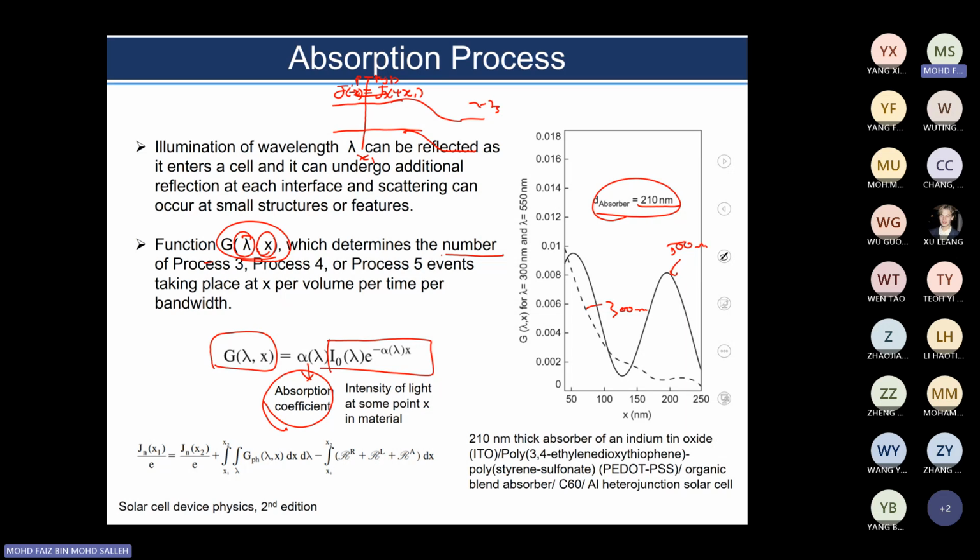However, in the PN junction, we give photon energy, and then there is electron excitation, producing electron and hole free carriers. And then we have the photovoltaic action, electron flowing one way, hole flowing the other way. We produce new electrons, or we increase the number of electrons. When you increase the number of electrons, from the current density equation, we know that the current density is increased, right?